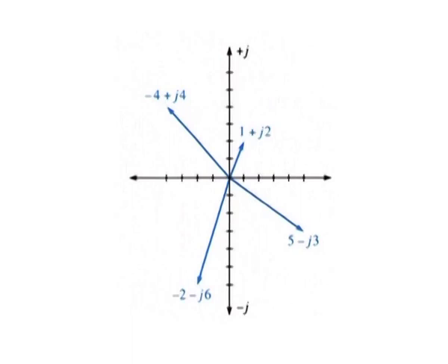As you can see, the rectangular coordinates describe the phasor in terms of its values projected onto the real axis and the j axis. An arrow drawn from the origin to the coordinate point in the complex plane represents graphically the phasor quantity.